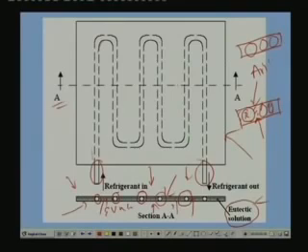That means when you have a lot of solution in the evaporator, a lot of external fluid, since it is a liquid, it has large specific heat, and it also has large mass because of its high density. So you have a large m Cp liquid which is cooled to almost the same temperature or a few degrees higher than the evaporator temperature. That means you have an evaporator which has a large thermal capacity and which is cooled to a low temperature. Now let us say that there is a power cut. If there is a power cut, then refrigeration is not provided, the refrigerant system does not work.